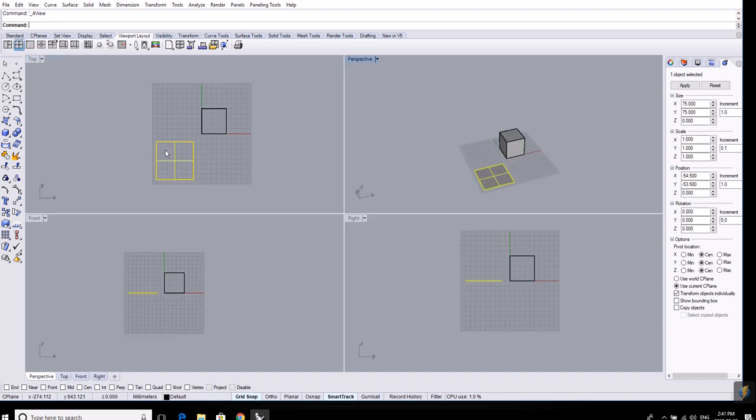If we want to use this plane as a cutting object, we can go back into our geometry. Let's look at the front view, and we're going to rotate it. We're going to use the box edit again, the rotation tool, and we're just going to put a simple angle in there, 22.5, which is half of 45 degrees. I'm going to try it on the X first, 22.5, and see what happens.